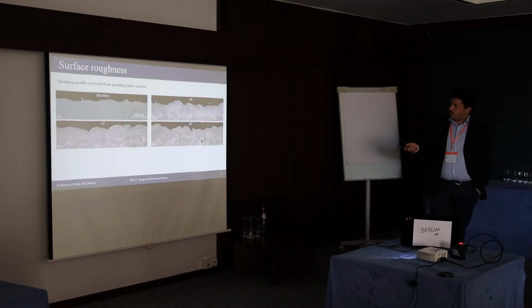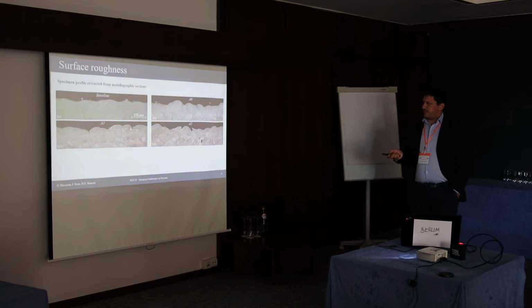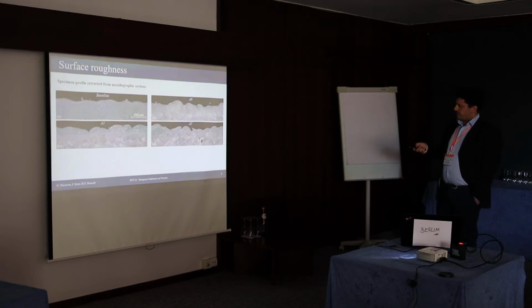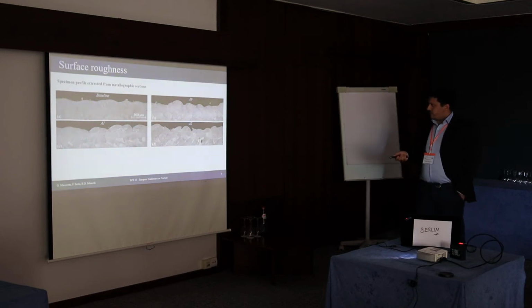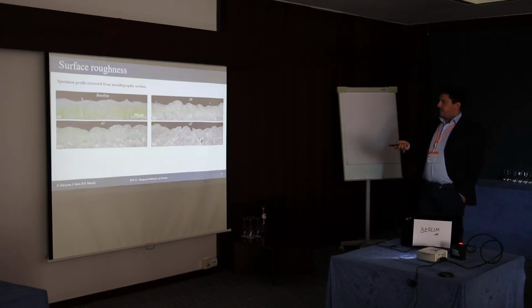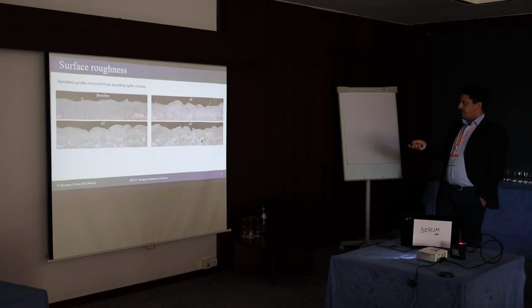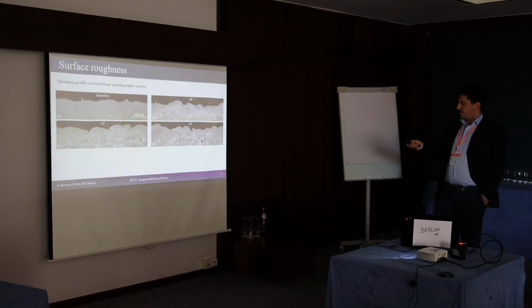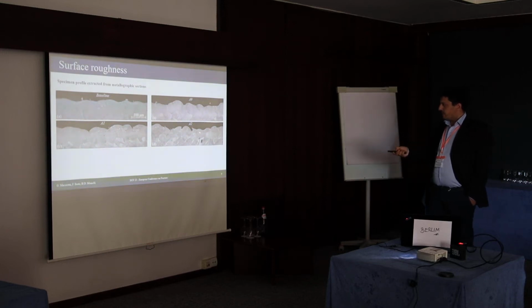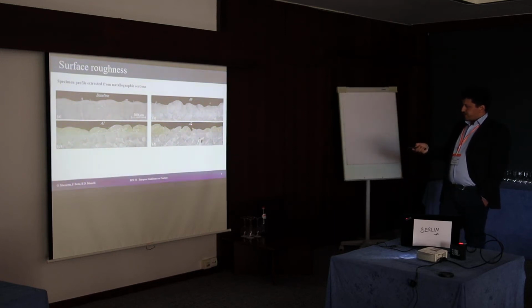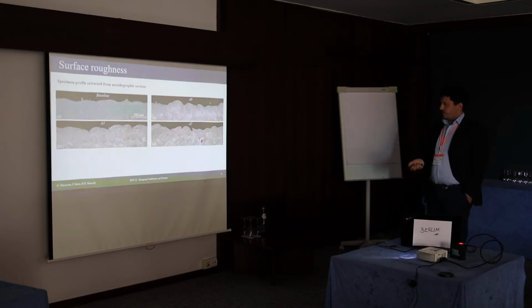If we look at the surface of the specimen, here we can see a metallographic section carried out in the longitudinal direction. Here you can see the melt pools, and the build direction is on the horizontal line, and you can see the baseline, A0, A1, and A2. You can see that the surface of the specimen has a smooth waviness in the baseline case, while this waviness becomes more pronounced, with steeper valleys, passing from A0 to A1 and finally to the A2 condition, where we have really steep valleys with, at their root, regions of high stress concentration.